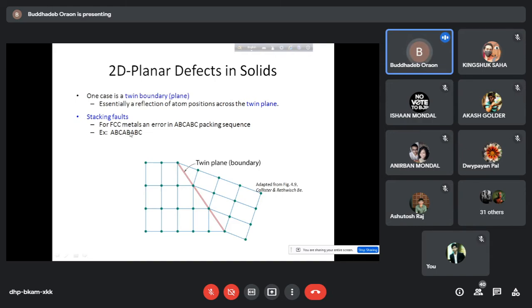So you see here C is missing. So atoms are actually arranged by stacking in a particular plane. If a particular plane is not present, then there will be a fault there, and a different type of structure may occur there. So if this stacking fault is there, then we say these are two-dimensional defects.